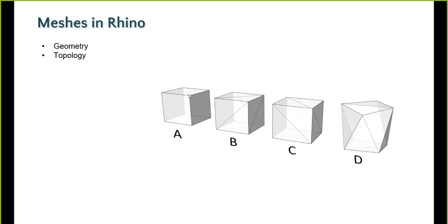So say I had these 8 points in space, I can create this outside mesh in any case. I can also create mesh faces that connect inside, where in this case, every edge in every case is shared by 2 faces. In that case, if you connected a point from this corner to this corner to this corner, you would have a mesh face that follows the same sort of rules as the other faces. It's counterclockwise in the list and connected to the same number of points, but it would cause this edge to share 3 faces.